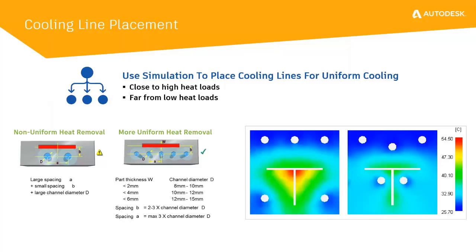Design variations can be virtually tested in Moldflow to determine the impact that changing the cooling layout or adding baffles and bubblers, for example, to critical areas. Moldflow also uses the thermal profile from the cooling analysis to determine the impact on shrink and warp.